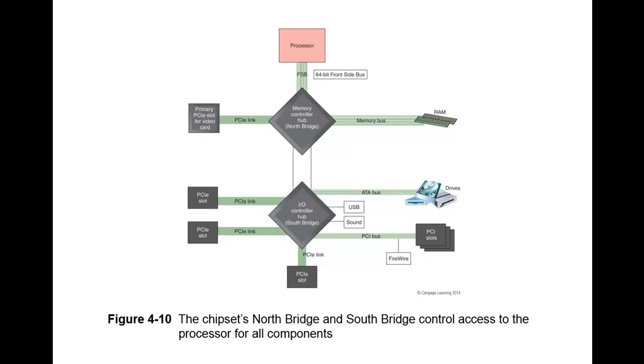We also have the Sandy Bridge chipsets, and these chipsets have the memory and graphics controller in the processor, whereas in the previous one we saw that these were both handled by the North Bridge. So just know that the Sandy Bridge architecture uses a single chipset hub called the Platform Controller Hub. In this hub, you'll see it controls things like the PCI Express cards, the SATA, any high-def audio, your USBs, your Ethernet. Those are handled on that Platform Controller Hub rather than the South Bridge hub.